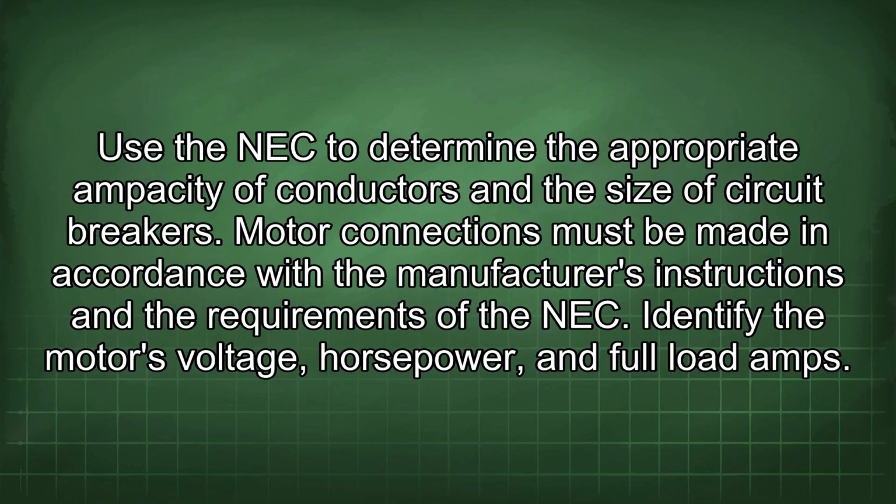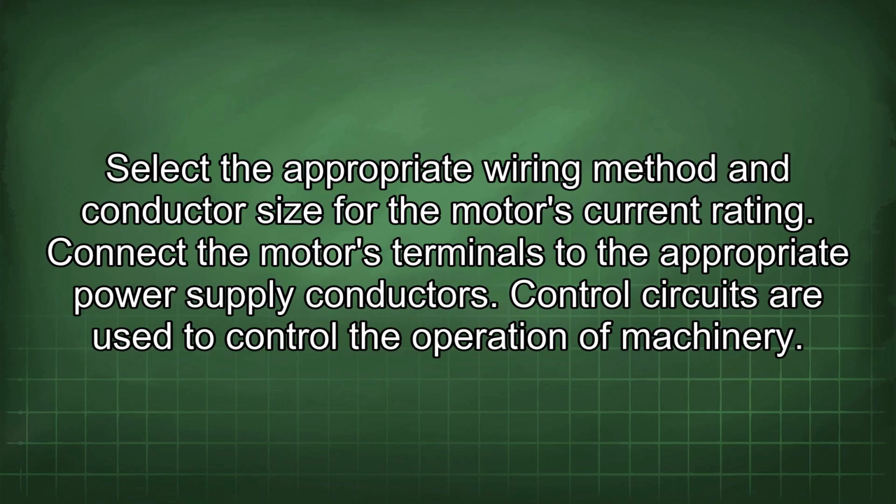Motor connections must be made in accordance with the manufacturer's instructions and the requirements of the NEC. Identify the motor's voltage, horsepower, and full load amps. Select the appropriate wiring method and conductor size for the motor's current rating. Connect the motor's terminals to the appropriate power supply conductors.